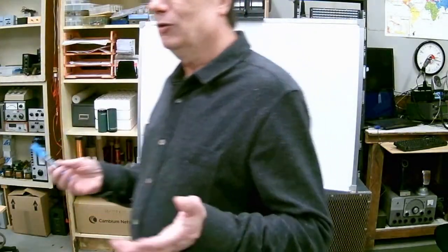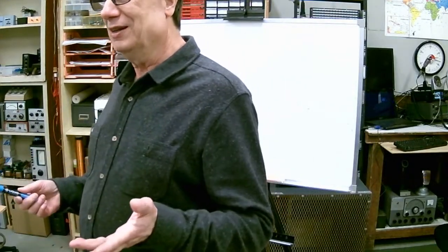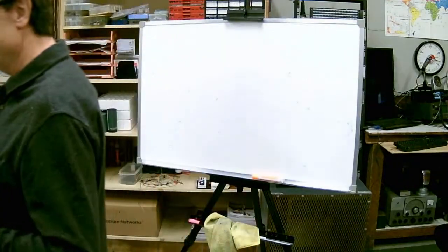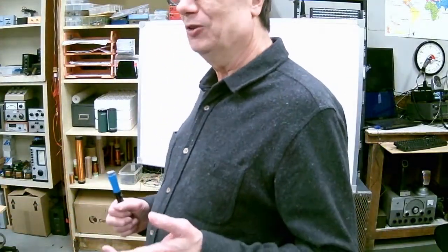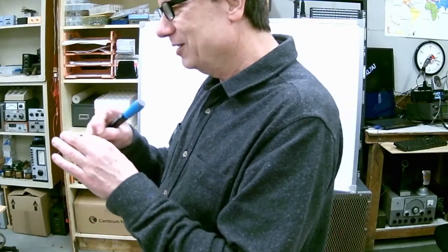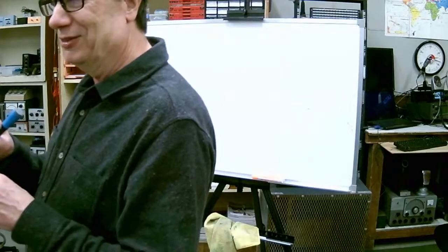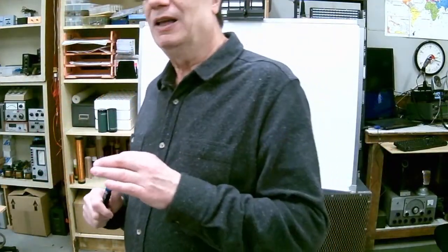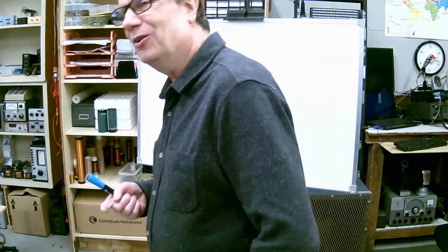Well, the crystal radio is nothing more than a demodulator. It's got a tuned circuit, and then you got some sort of detector. Nowadays we use a germanium or silicon detector. Back in the early days of radio, you used a cat's whisker, which was just a chunk of galena and a little wire that you moved around on until you found a sweet spot, and at that point it became a diode. So you just made this diode on the fly. What's galena? It's a lead ore compound, which is a predecessor to older semiconductors.